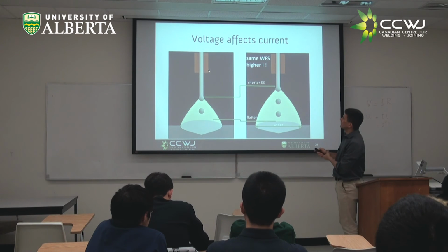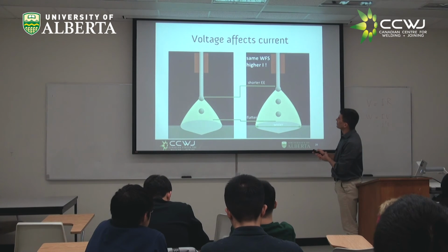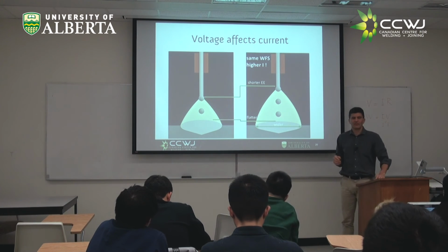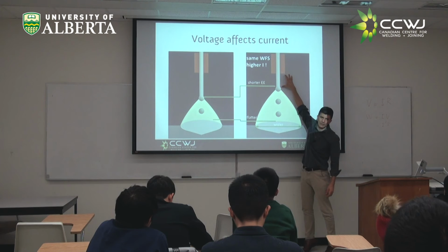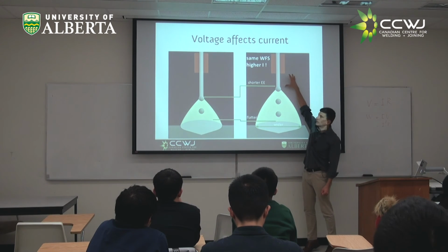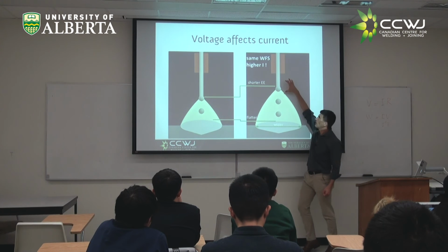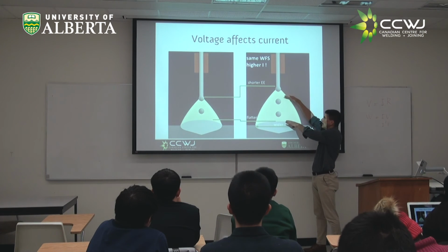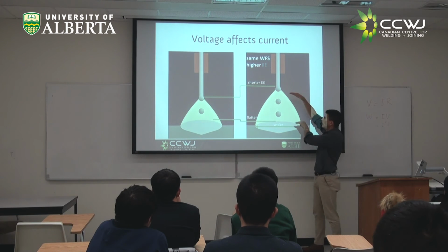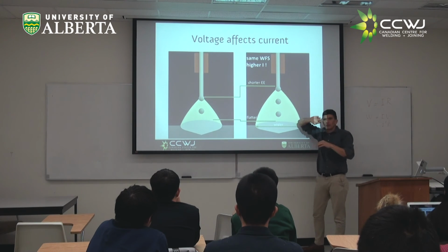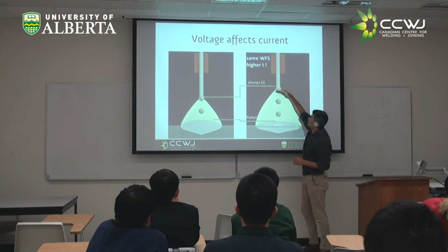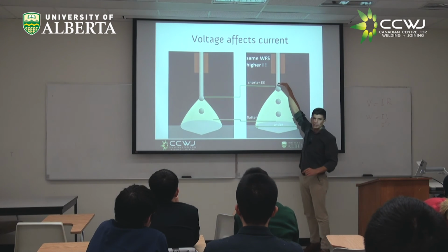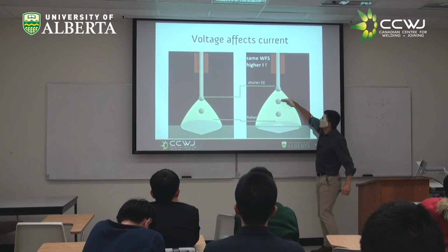So imagine I increase the voltage, right? And the voltage, if you remember, there is relatively little voltage in the stick out. If we were to have a half-an-inch stick out, we have about 2 volts here. And if we were to have a 6-millimeter arc, we have almost 5 volts here. So if we increase the voltage, the arc wins, and the arc gets longer. If we increase the voltage, the arc gets longer.